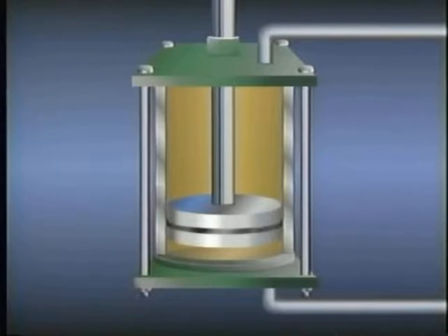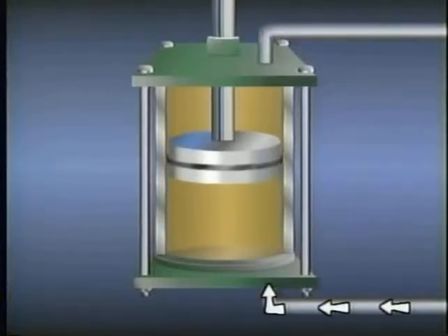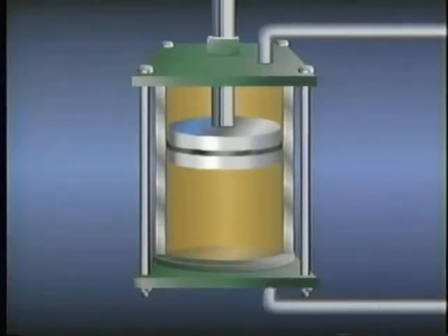The differences are that the cylinder on this double-acting actuator doesn't have a vent, and it has two fluid ports instead of one. The two ports allow fluid to enter and exit on both sides of the piston. Fluid can enter this port to move the piston up, and it can enter this port to move the piston down. When fluid enters the lower port, fluid flow pushes the piston and piston rod upward. At the same time, an equal volume of fluid flows out through the upper port.